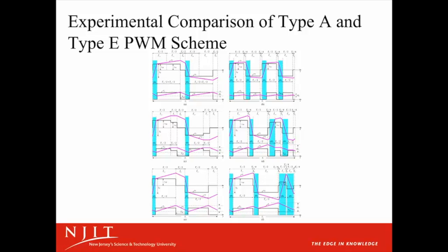On the other hand, for the type E PWM, 3 of the off intervals adjacent to the narrow pulses combine into one, resulting in a large current ripple. For instance, at the angle equals -30, two of the pulses on the secondary side disappear so that the off-time intervals merge into one large interval.